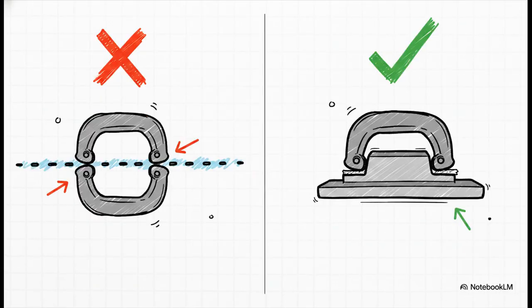I really want to hammer this point home again. Please do not pick datum features just because their individual dimensions happen to be super tight, or because they represent a really convenient imaginary axis in SolidWorks or whatever you use. That's not what datums are for. Datums exist so the physical part can be reliably fixtured, stabilized, and measured in a reasonable coordinate system. If you select non-functional surfaces, you will instantly compromise how that part fits and functions in the final assembly. And believe me, the assembly team will definitely let you know about it.